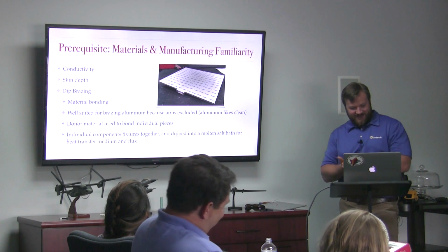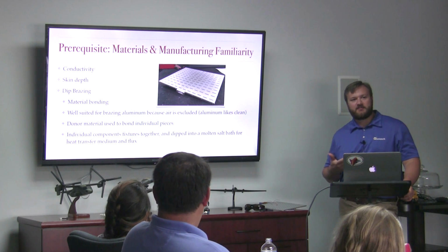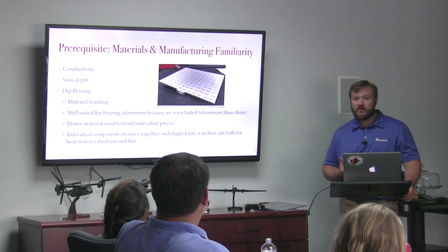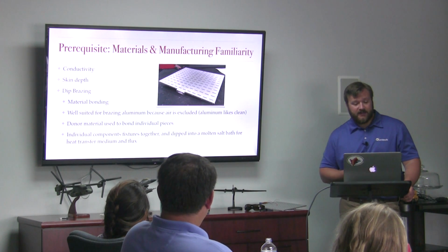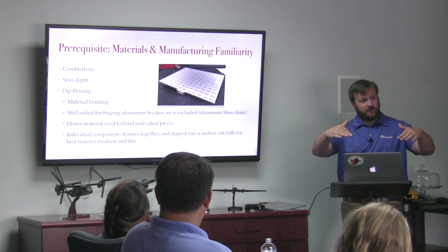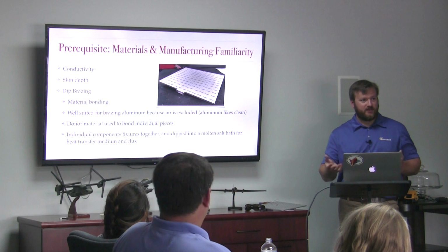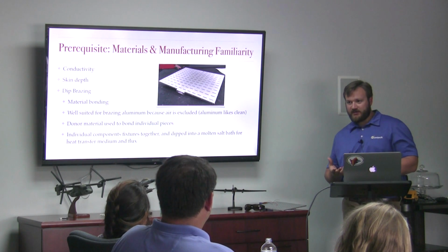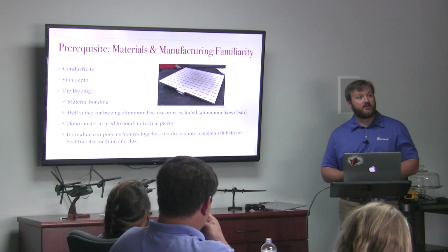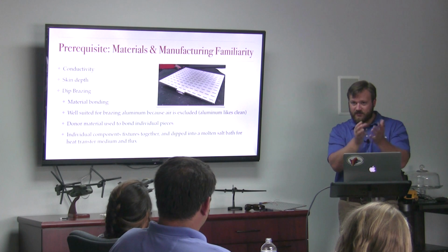That's without a doubt. Something that's neat about the salt bath is it's preventing oxidation. So it's inhibiting oxygen from creating impurities in the actual bonding. It's also allowing that donor material to flow. It acts like a flux. When you solder, if you don't have flux, has anyone tried to solder without flux before? It's horrible, right? But when you have a flux core solder, or you apply flux before you solder, it creates that nice, clean meniscus.